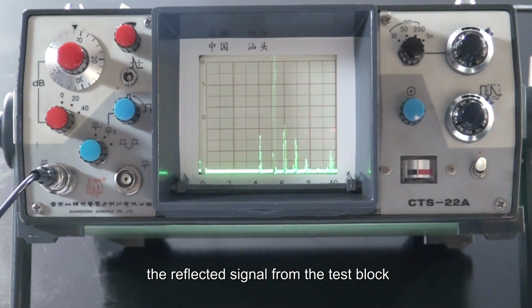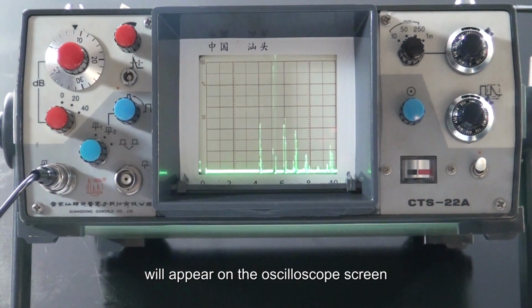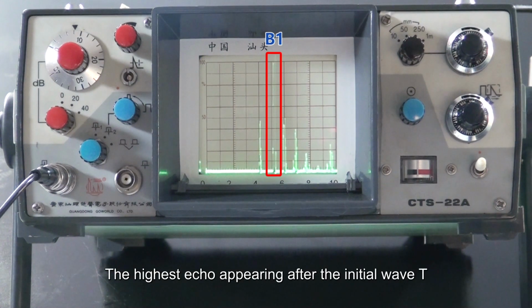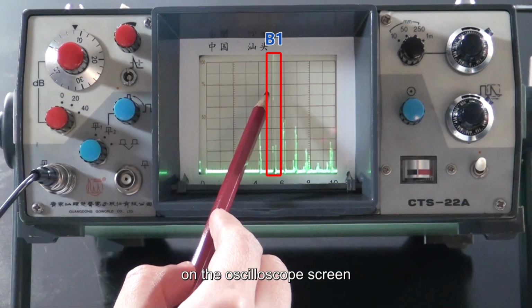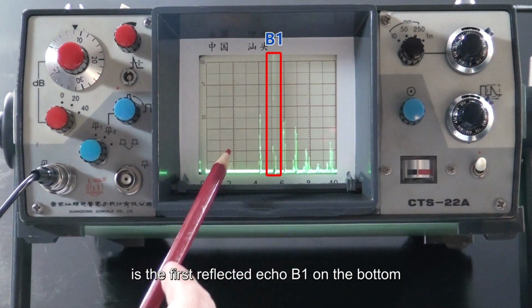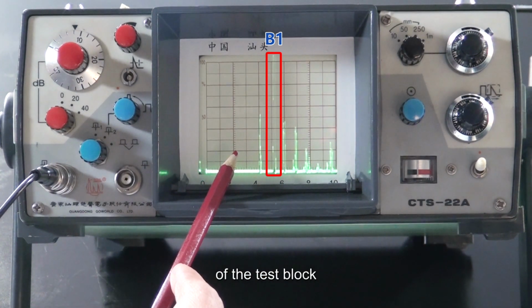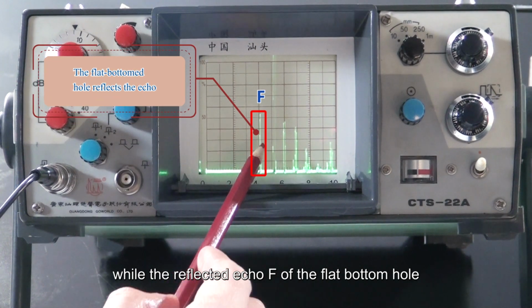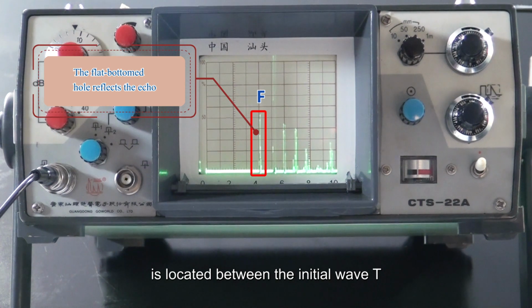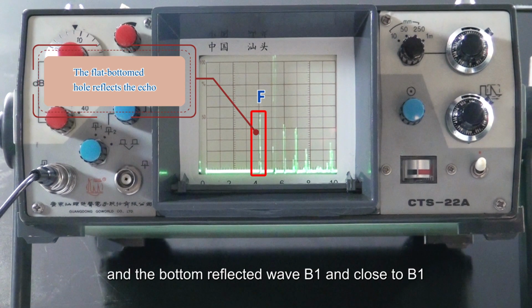At this time, the reflected signal from the test block will appear on the oscilloscope screen. The highest echo after the initial wave T on the oscilloscope screen is the first reflected echo B1 from the bottom of the test block, while the reflected echo F of the flat bottom hole is located between the initial wave T and the bottom reflected wave B1 and close to B1.